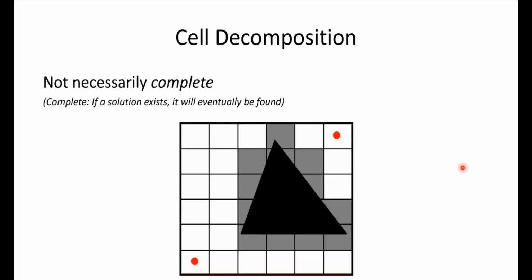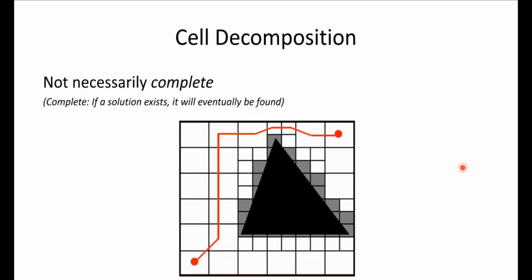And then I'll do the same process. I'll iterate over all of those new cells. If those are completely full, then I just keep them as is. If it's partial, I split it. And if it's free, I leave it alone. And so with that, I can decompose my space into something that now has a solution. And so this act of taking my partially full cells and then splitting them up into smaller cells is something called quad tree decomposition.